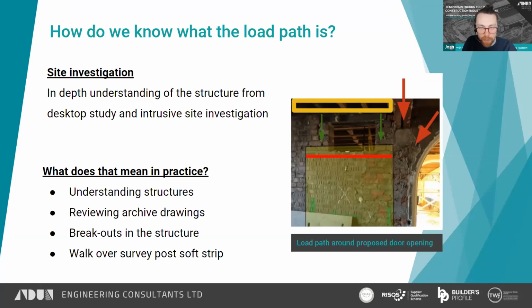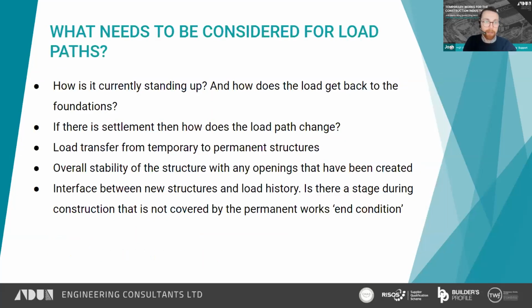And it's also a good idea to have a good walk around and a walkover survey post soft strip so that you can have a good look at the bare structure and the structural elements that you have there. This is going to give you a good understanding of how the structure works and what the load paths are.